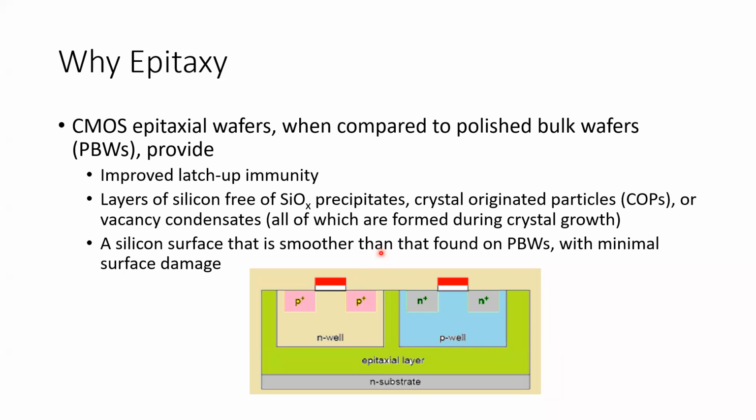Latch-up basically means the resistance between the power and the ground decreases, so they are basically connected. They will be leaking, and the device will stop working after some time. By using this epitaxial layer, which has high purity and low defects, it will improve this latch-up immunity.